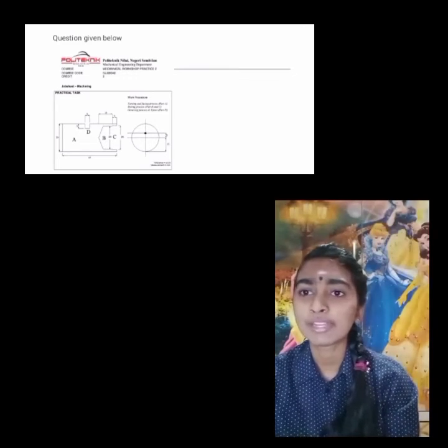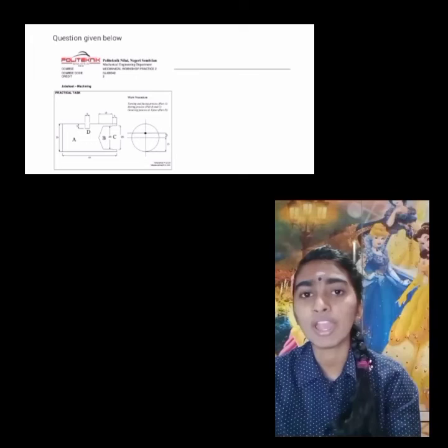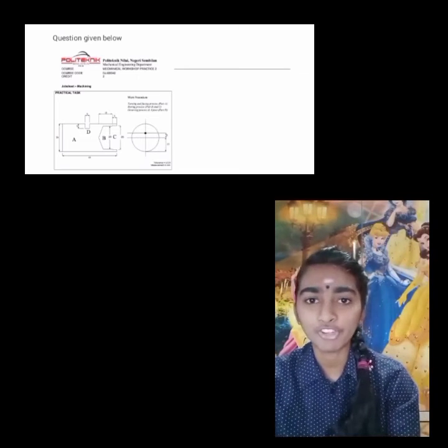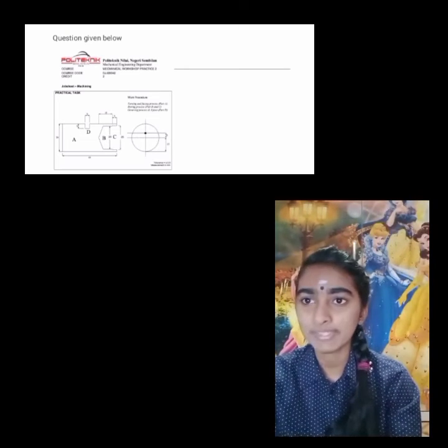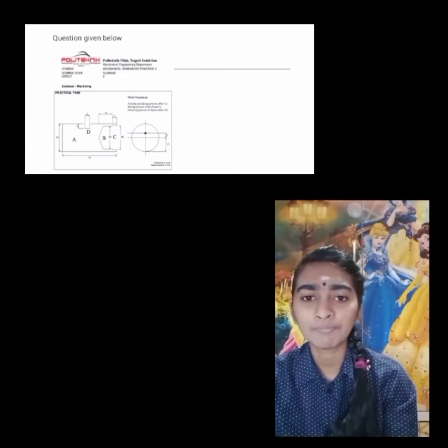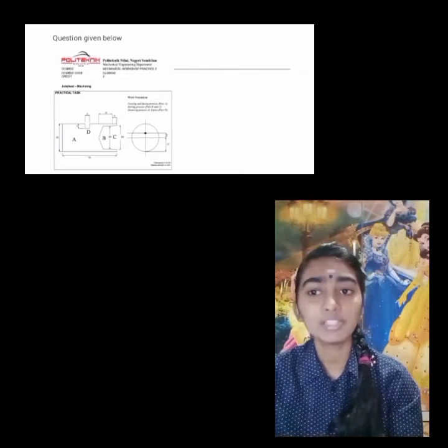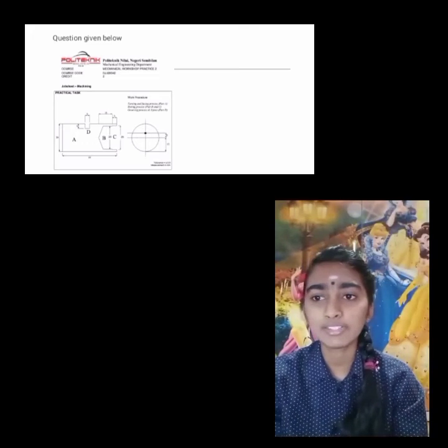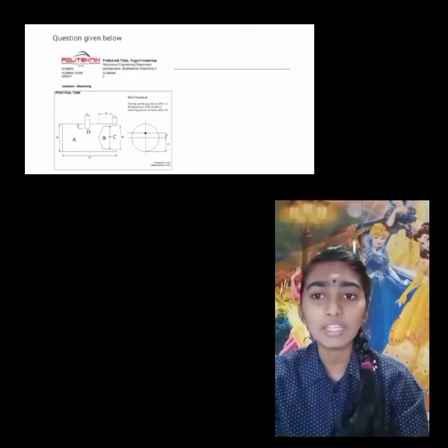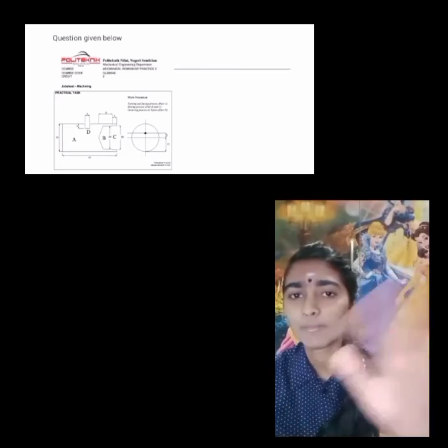The first step, we clamp the workpiece and mark it in a good position before starting the operation. After that, we start the facing operation to reduce the length of the workpiece. We did the facing operation before any other operation to make the workpiece flat and remove the marks. After the facing operation, we did the turning operation to decrease the diameter of the workpiece. Finally, we clean the workpiece using a steel brush and sandpaper.